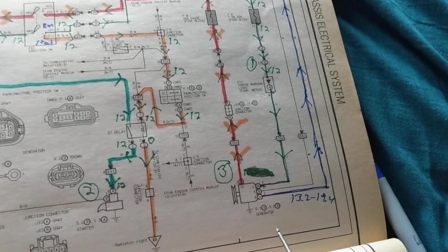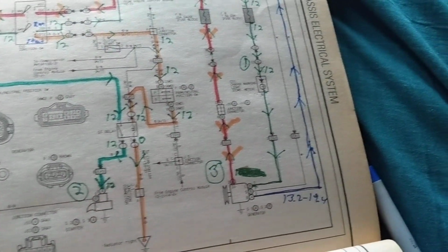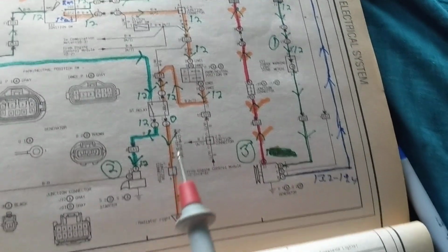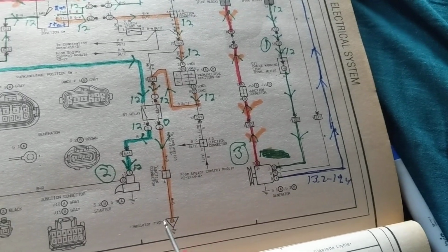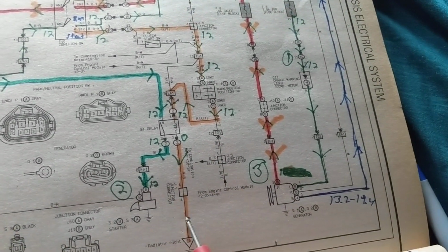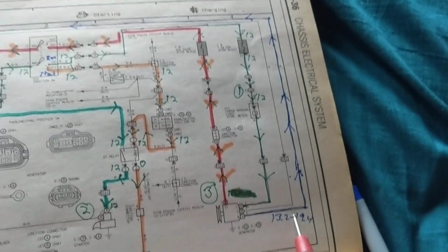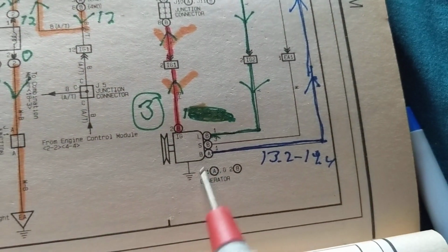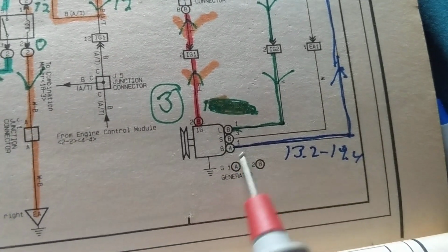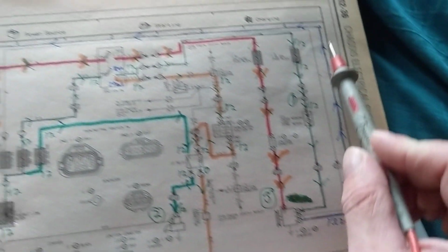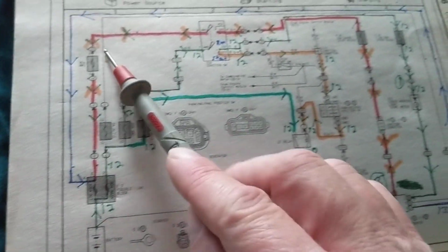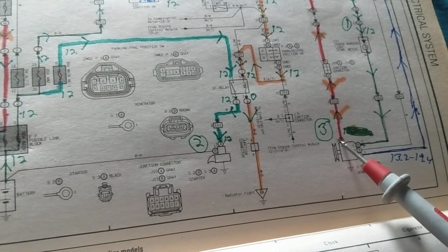Now, before we get to troubleshooting, and it'll be in a video, I'm already at 17 minutes. What happens after that? You started the starter motor, the flywheel, the crankshaft, the pulleys, the alternator started. When the alternator started, I'm still in the start position, remember. Still holding my key in the start position. What happens? Guess what? Now, from this one, a BA position over here, B1 position, 1A they call it. Go over here, we come back through this fusible link, 100 amps, which you use in the first place, through the ignition switch to give it 12 volts.